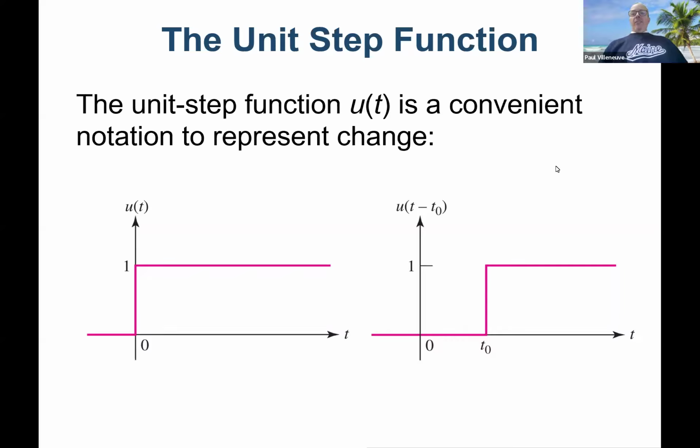So we are now adding a concept, and this is just a mathematical construct, which makes our analysis a lot easier if you understand what these functions are. It's called a unit step function, which is just another way to add a switch. So a DC source goes from 0 to whatever the DC value is, usually at time t equals 0. That is mimicked by our unit step. So instead of having a circuit with a switch transitioning at t equals 0, normally what we would do is we would specify a unit step input for a power supply.